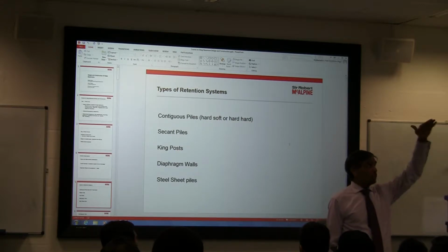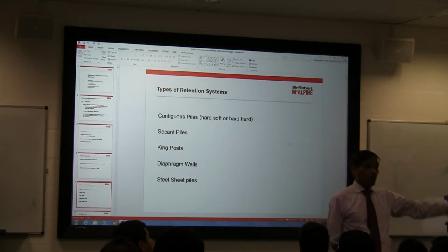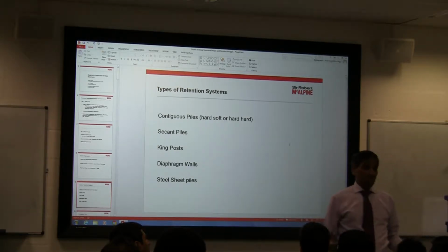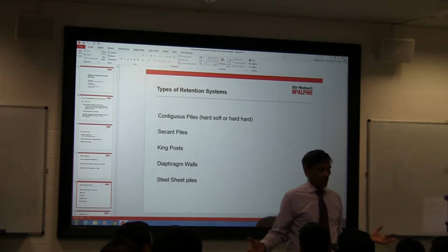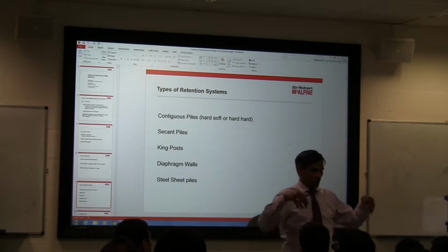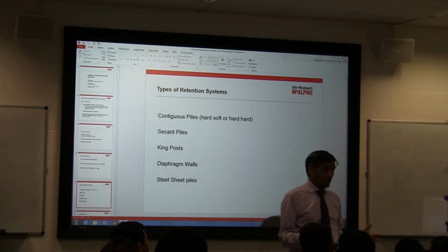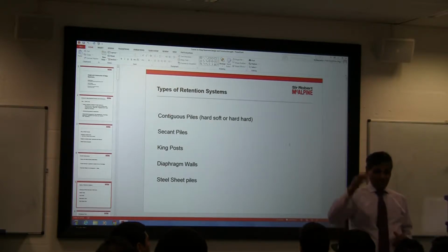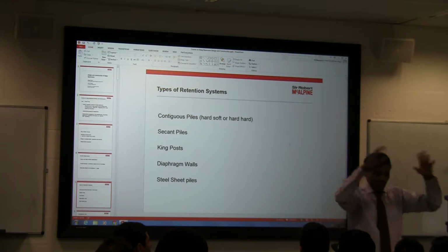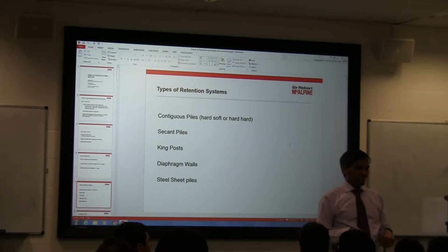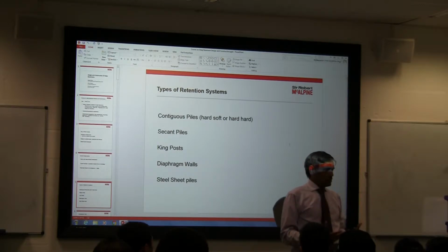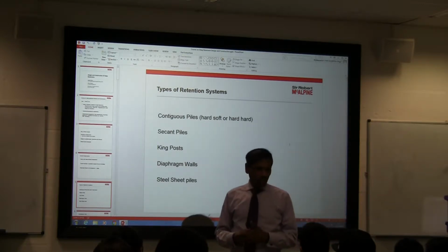That means if you are at ground level, you only have a basement wall there, roughly one basement deep. And the client comes and says, I want to put in a 6-level car park, and a gym, and a swimming pool, everything below, which is what we've done on hotel buildings. Now we have to think about whether to start digging from that level or this level, because remember, we still have a basement that is already there, and we are working in the basement. We are deepening the basement. So what should we choose? What retention system should we use?